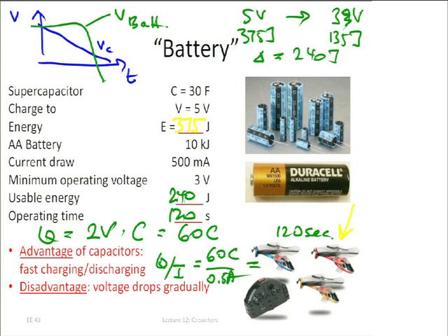Yes, they do wear out, especially, well, not all of them, but certainly these supercapacitors. Every chemical capacitor, electrolytic capacitor, supercapacitor, they do wear out. If you have an audio system, very often when it is 5 or 10 years old, it starts exhibiting a hum. It's very often that the capacitors went bad. If you unsolder all the capacitors and replace them with new ones, you fixed your stereo.